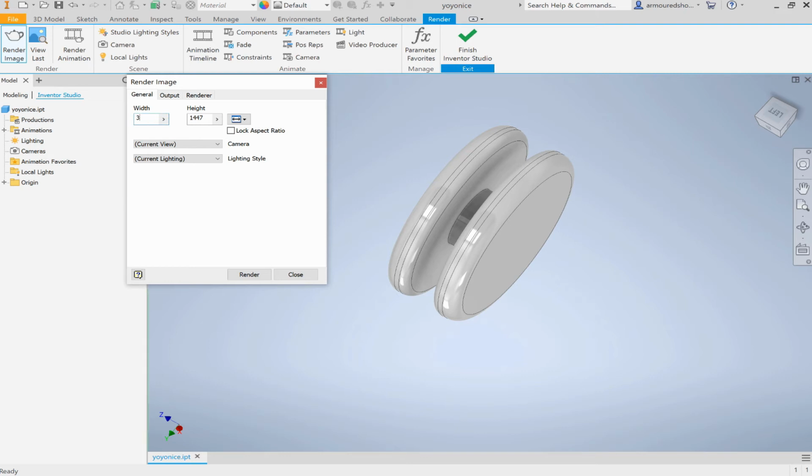Then the other thing you need to do is choose the resolution that you're going to render at. If I want to render at 4K, it would be 3840 by 2160. It's just the resolution of a 4K screen. Now, I'm not going to render with that because that's a lot of work. So we're just going to render at 1920 by 1080, which is about a quarter of the pixels of 4K, which is why we're doing this. So in theory, it'll be easier.